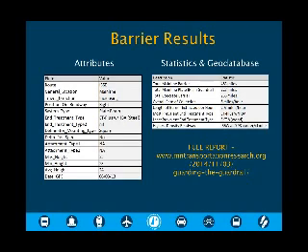Some statistics on the right that I'd like to mention. We found out we had 483 miles of total barrier, and 227 miles was plate beam. And we extracted at a rate of 5 miles per hour. Kind of just good to know. We also extracted 250 condition points that were included. The condition points included things like broken posts for plate beam and spalling concrete. Those issues now have either been fixed by our maintenance crews, or we will be continuing to monitor the asset.